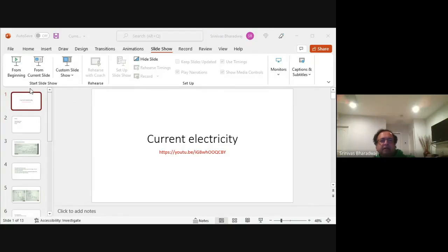So let me start here and go: plus 2 minus 4 minus I times R2 minus I times RL minus I times R1 equals 0. I go in one full loop around it. So plus 2 minus 4. Remember, you go from the little bar to the upper bar, you say positive, right? So that's how it's done.